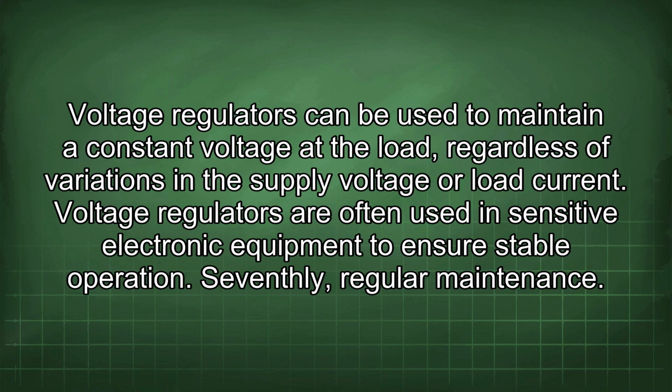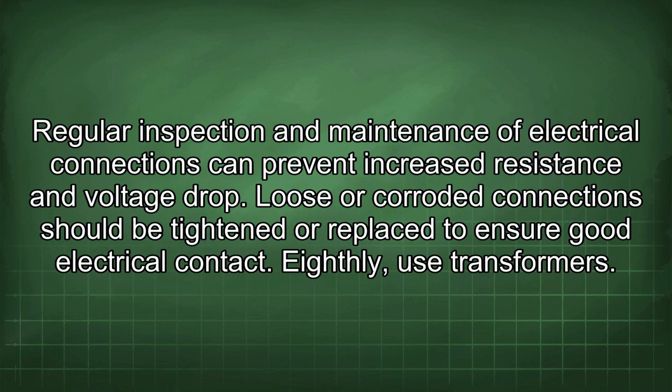Seventhly, regular maintenance. Regular inspection and maintenance of electrical connections can prevent increased resistance and voltage drop. Loose or corroded connections should be tightened or replaced to ensure good electrical contact.